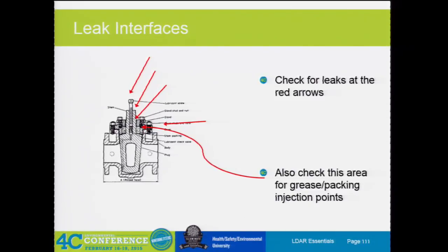And a lot of times when these things leak and you pack more grease into them, same way with an orbit valve or something, when you just start packing grease into these things, you'll see them just repetitively leak over and over and over. So, as I said earlier, grease will sooner or later be saturated with the VOC and leak out. It's not a good sealing method, but it works for a while.